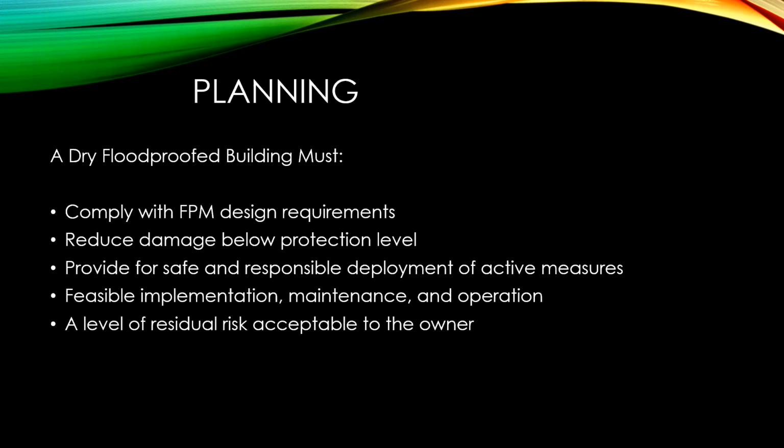So we have to comply with our local and state floodplain management requirements, reduce damage below the protection level, provide safe and responsible deployment of active measures, because we have to send somebody out when we get a flood warning, and then be able to implement them, and then have plans for maintenance and operations.